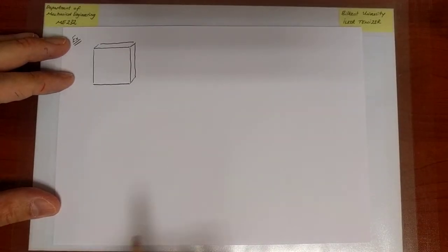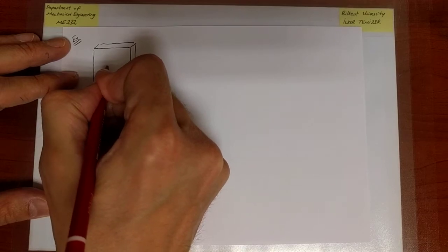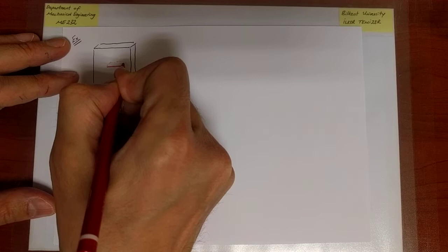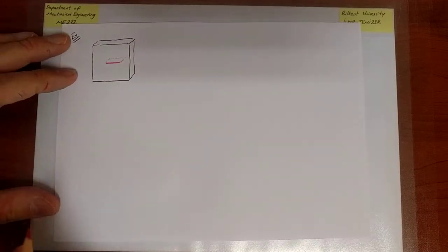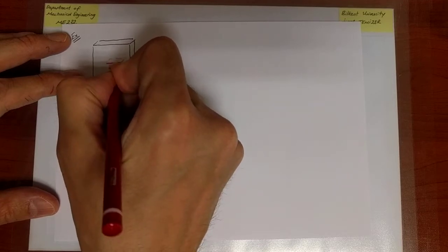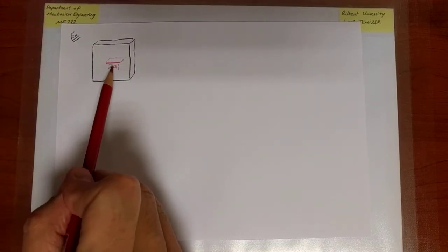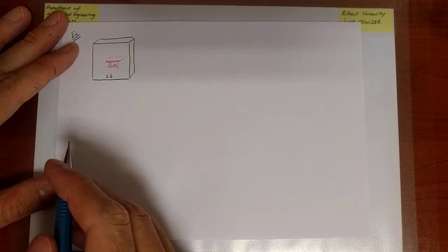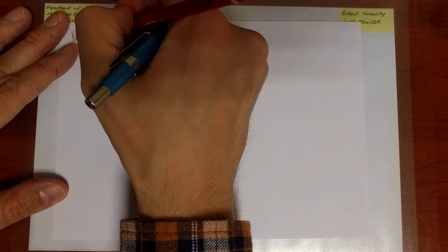Okay, so we have a plate with a central crack, not necessarily small. It is a through thickness crack. If it were not through thickness, penny shaped, I have equations for it as well, but it is a through thickness crack, classical scenario, of initial size a_i. Half the width is b for the plate, and we are pulling on this plate.